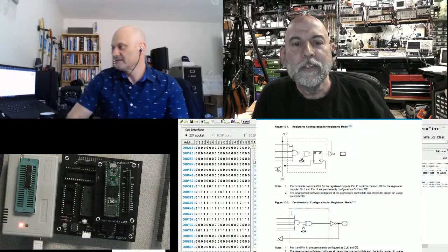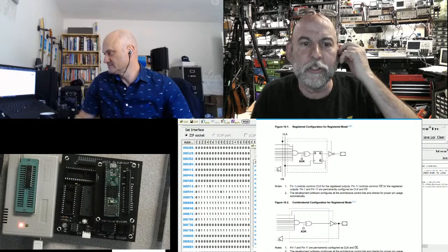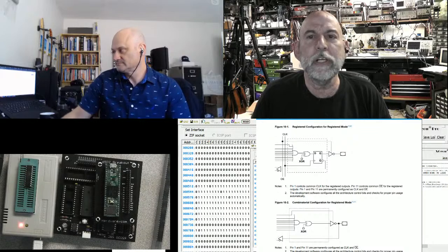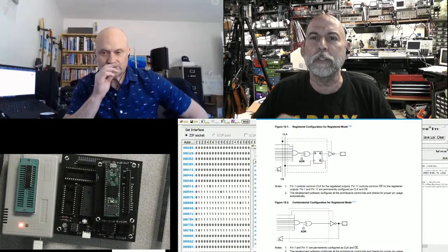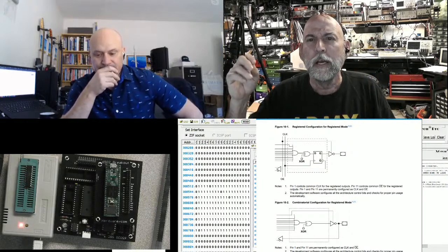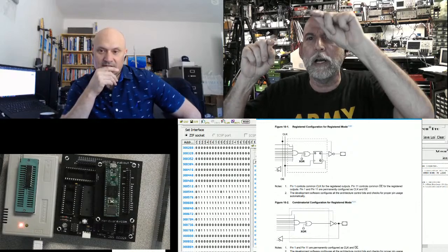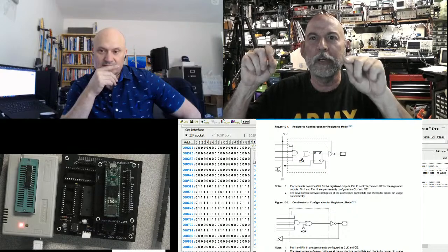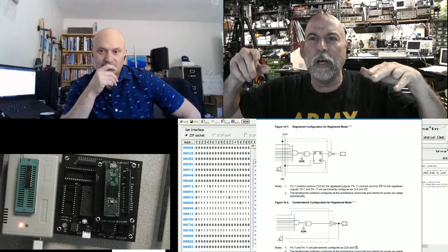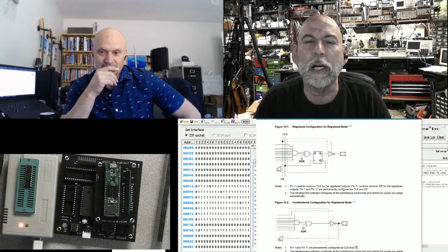So somebody asked, the 32 megahertz 6502, can it pause like a 65C02? And the answer is yes, it can. But the secret is it's not really pausing. There's a 160 megahertz clock, if I remember right, and 32 meg was a division of that. So that real fast clock is running the whole time, but I'm monitoring the clock that I get from the main board. If it clocks, I go ahead and do my thing. If it pauses, I'm just sitting here with the master oscillator, but the state machine is paused. So yes, I can go as fast or as slow as whatever clock is given to me.